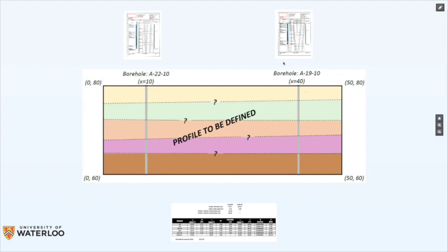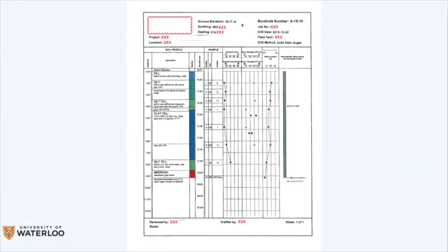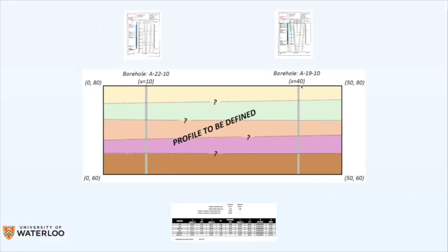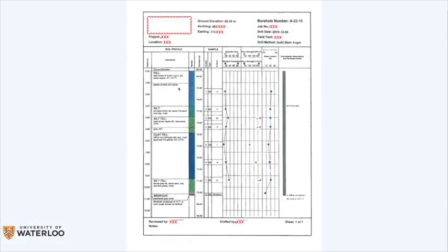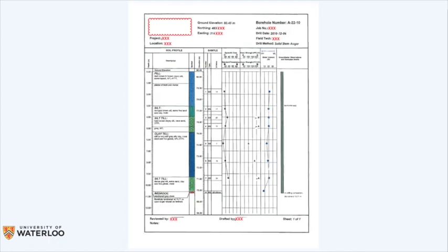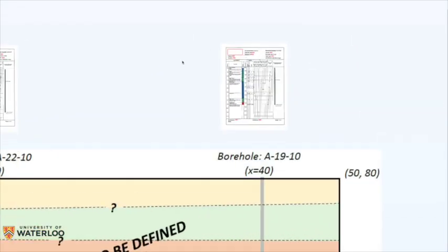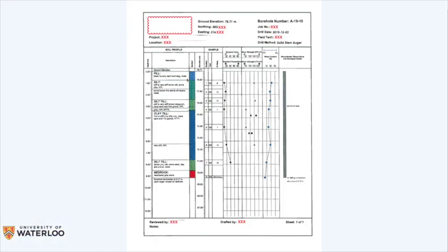And for the second borehole it is 78.71, so that means something like 1.29 meters below this surface. Okay? We're going to do that in the software, and then we're going to connect the points to create the layers. So we have here the fill, and here the same material, you see, fill.